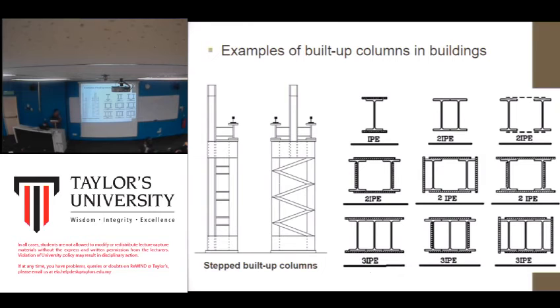As you know, the crane carries loads, maybe lifting certain goods or items, so it's quite heavy. This part of the column transfers the load from the crane to this beam, and then from the beam to the column and to the ground. But for supporting the roof itself, you only need this column. You don't need a huge column to support a roof, because roofs are not that heavy compared to other components.